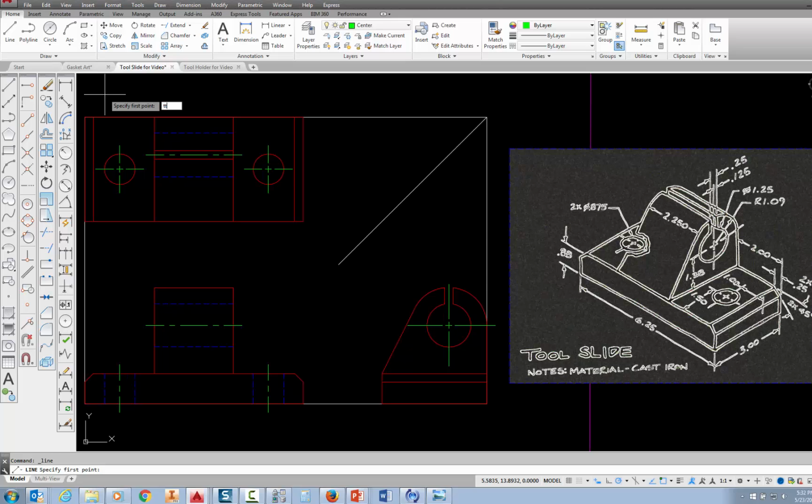TT and press enter. And I would come to the endpoint until it says, just park there until it says endpoint. Follow the dotted line across, pick at the miter line. I want to follow that straight down, and at that point I'm going to pick, oh I'm sorry, I got the wrong line. Let's do that again. I'm going to pick, type TT, and enter.